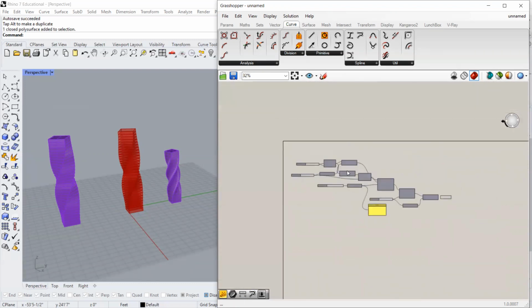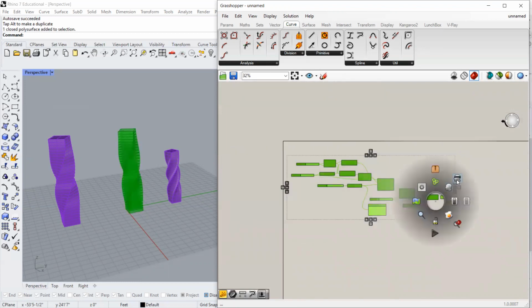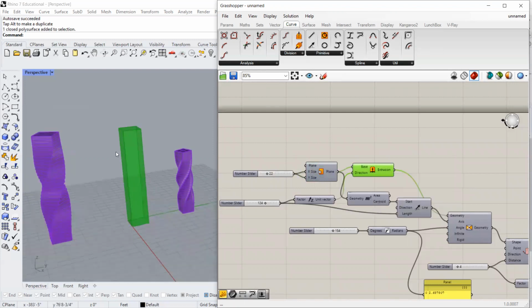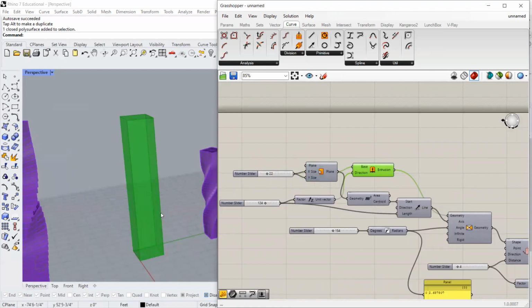When you say on an angle, do you mean this original extrusion on an angle? Yeah, that's what I was trying to do. So yeah, you need to pick a different vector. Your vector can't be, well, one, you could rotate this, but that's probably not what you want.